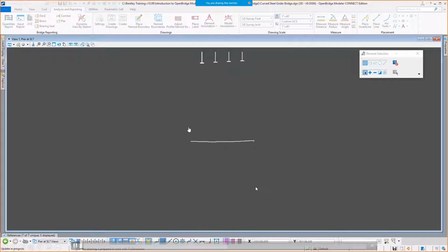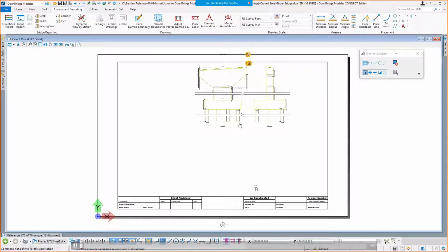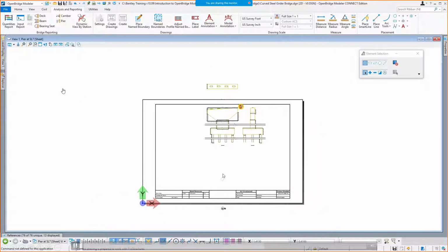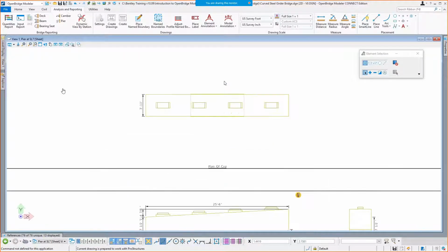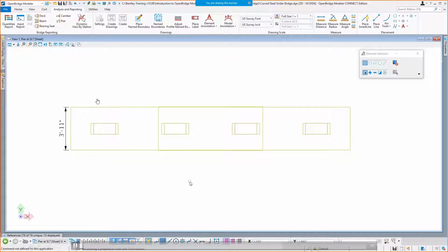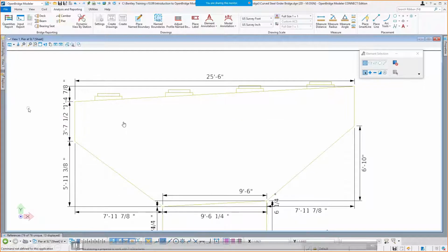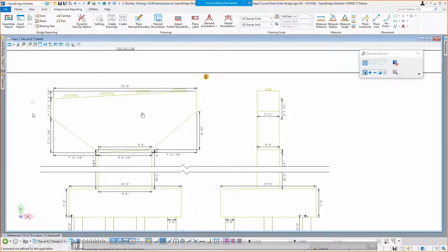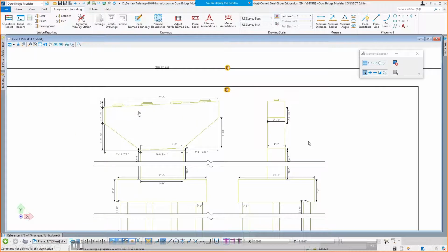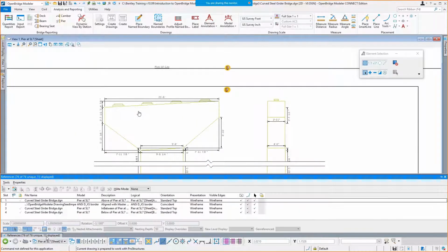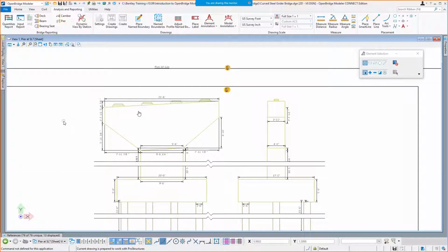So it went off, it created the drawing model, created the sheet model, it referenced the drawing to the sheet, went back to the drawing model, added all the dimensions, and then went ahead and threw us back in the sheet model. So it was going back and forth several times there, but this is, again, all live stuff. All these dimensions by default are associative dimensions. Again, so if the model changes, the drawing model changes, the sheet model changes, and the annotation would change as well.